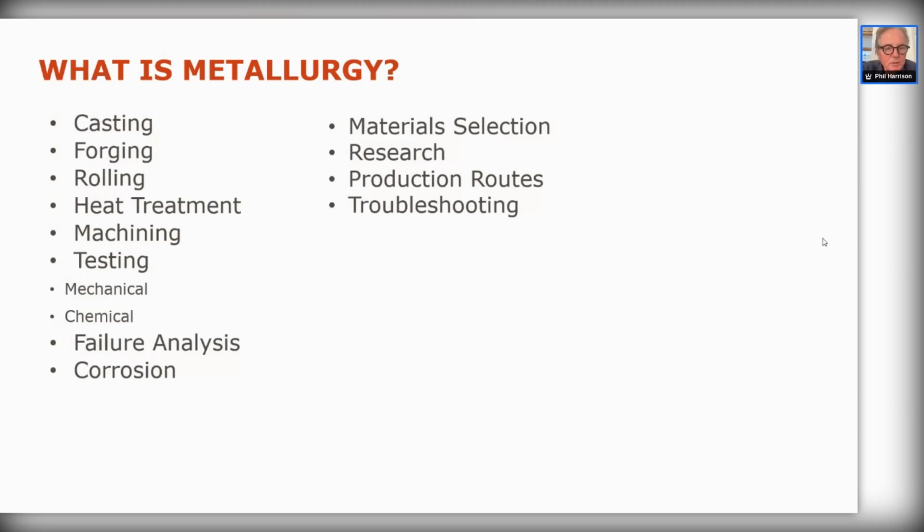This heats the metal up. The metal undergoes a process called recrystallization, where the coarse cast structure of the original casting is replaced by a finer grain structure. The forging and rolling further refine the grains in the material, and again densify the material. It's incredible, dramatically increasing the properties of these.